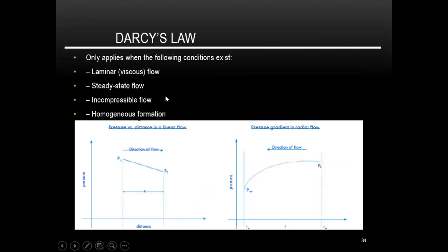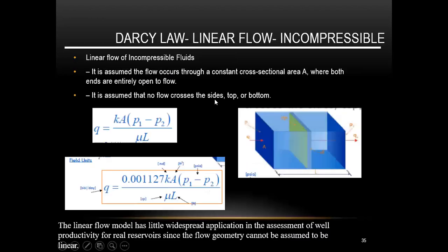And here, when we talk about Darcy's Law, it should have conditions. I mean, when we apply Darcy's Law, it should represent the real environment we are talking about. As you know, we are talking about steady state flow, incompressible fluids, which means oil, homogeneous formation, which means there is no change in the permeability and porosity throughout, and laminar flow.